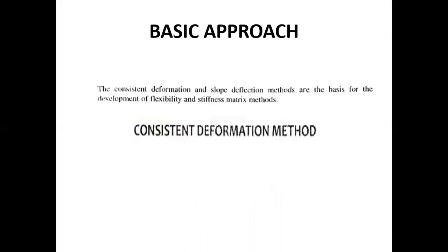Now, what is the basic approach for this? The basic approach for analyzing a structure using the matrix method is based upon the consistent deformation and slope deflection methods. Basically, consistent deformation and slope deflection methods are the basics of the flexibility and the stiffness matrix methods.